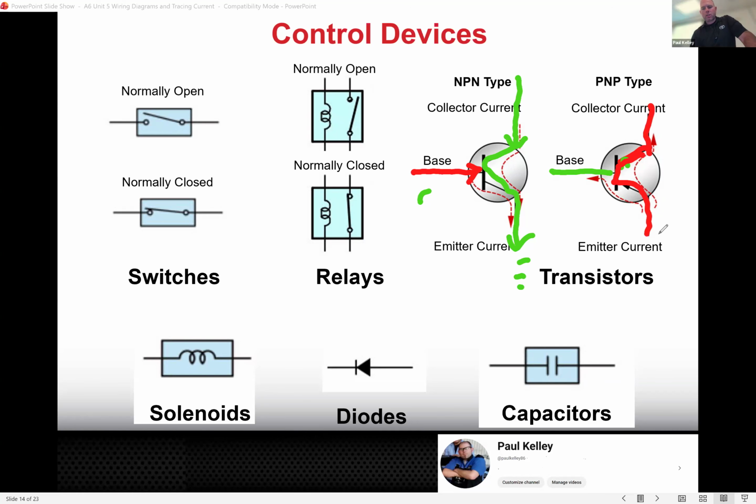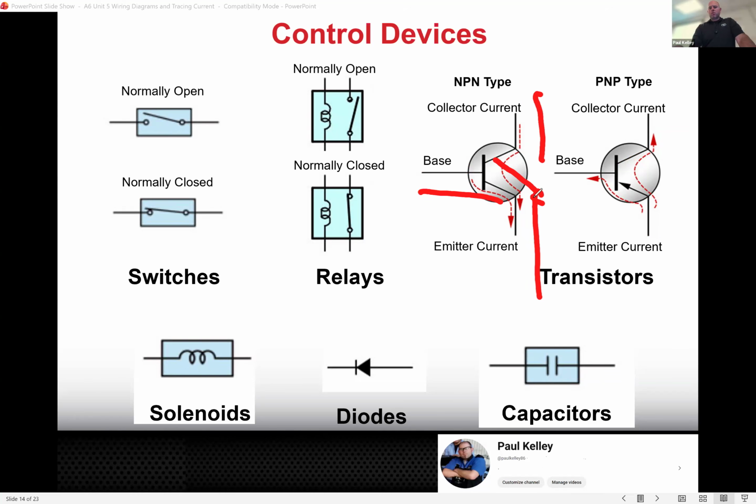It's kind of showing a little bit opposite because it's electron theory, right? But just keep that in mind with your transistors. If they've got the base current, it'll flow. If it doesn't have the base current, it won't flow. Honestly, we could have pretty much drawn it as a switch, right? The switch is open, but if we give a base current, the switch becomes closed. Cool?